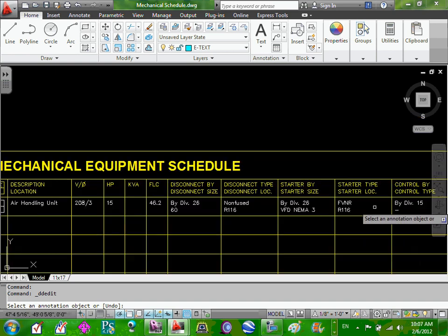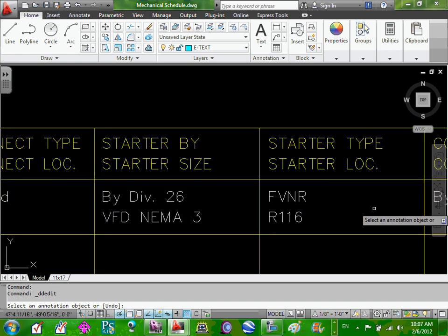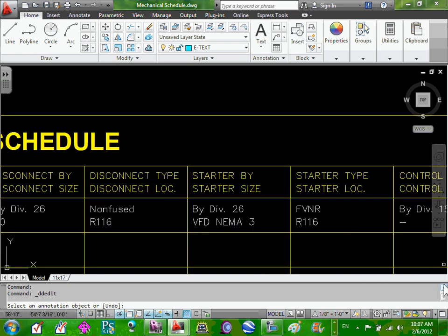Okay, so your options are VFD or NEMA, really. If it doesn't say anything about VFD or NEMA, and they say just snap switch, you write snap switch. All this information is right here in front of you. Or if you couldn't find anything about the control, they didn't say anything about the control, what does that mean? Provided by the mechanical contractor. So we don't provide it, so just leave it open.